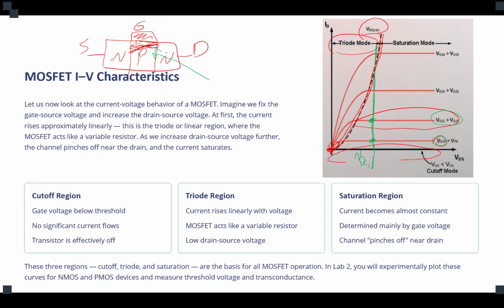So you open up a certain channel that the charges can jump through between drain and source, either way. Are we good? Now, when you apply a higher voltage between the gate and source, you have a wider channel, so you have more capacity to transfer charge between drain and source.